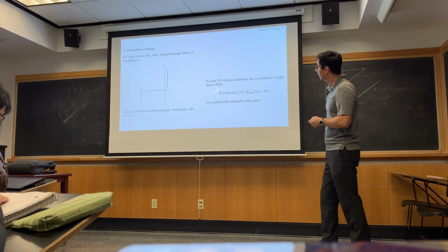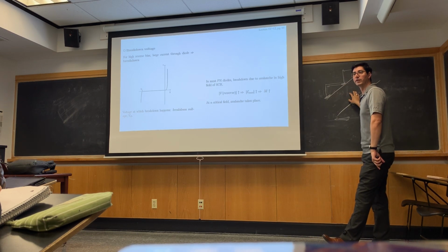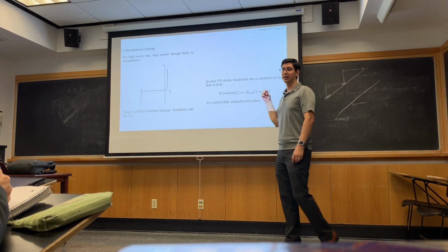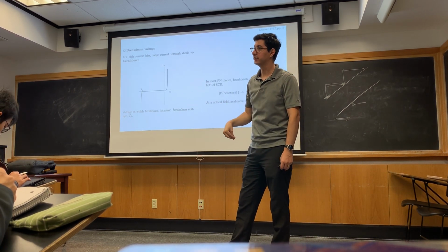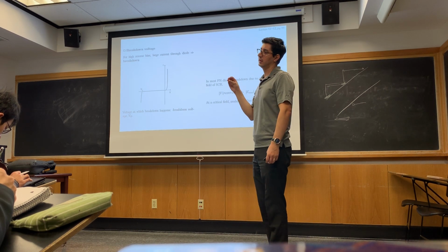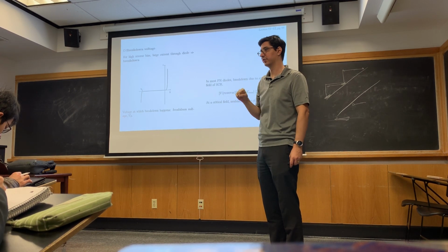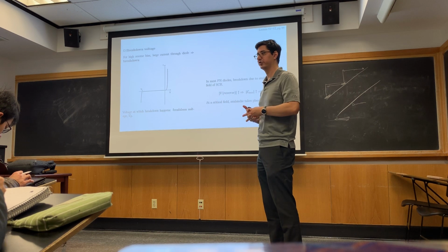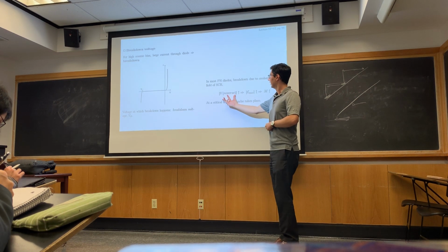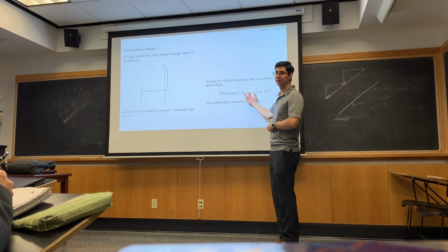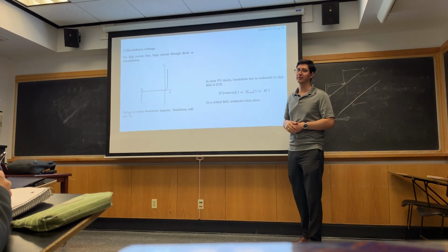Okay? So, avalanche goes with the electric field. The larger the electric field, the more likely the carrier will gain enough kinetic energy before scattering. If the electric field is small, then yeah, the carrier will travel some distance and maybe gain some kinetic energy, but then it will scatter, and that kinetic energy won't be enough to create an electron hole pair. Okay? So when the reverse bias gets large, the electric field gets large across the junction, and the multiplication constant increases.